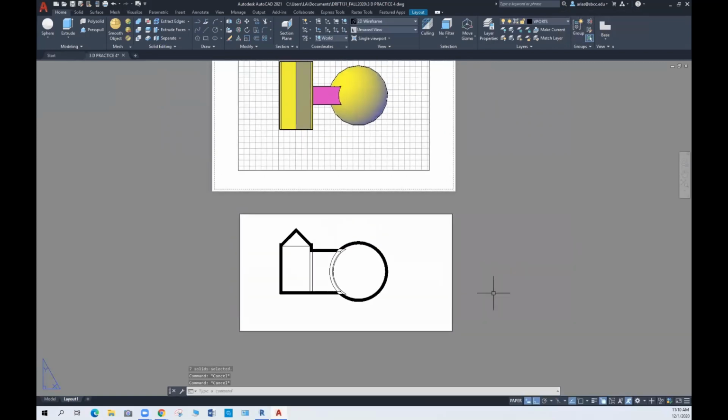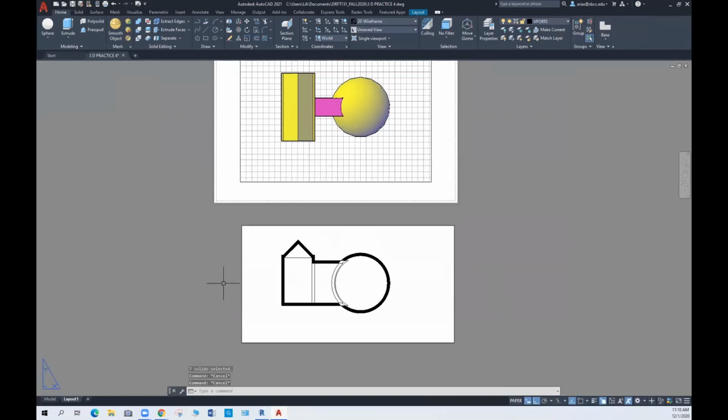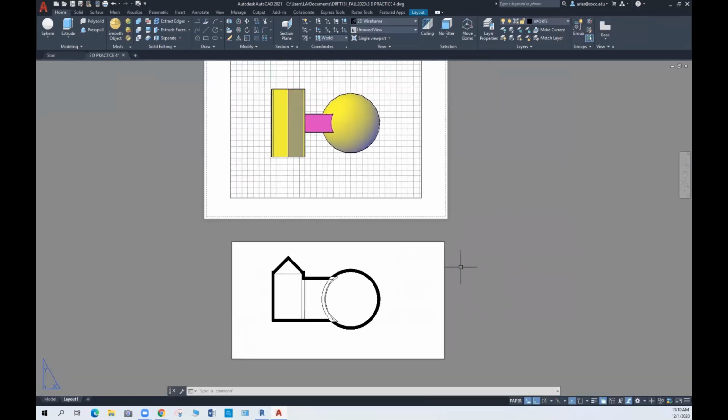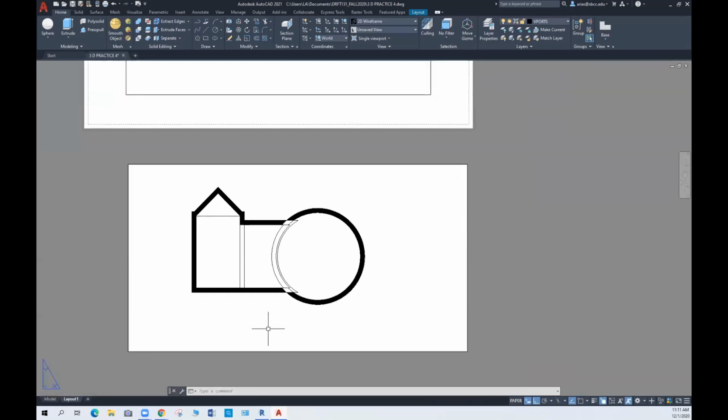And that's the section. So this time works fine. If it's not working in a view, just go back to model space and restart the solve view process, right? Because sometimes the solve view viewport that we create is not actually a solve view viewport, depending on what we have done. So to clean up, go back to model, delete the viewport, delete the layout, go back to model, and restart the solve view process. And now I get that.